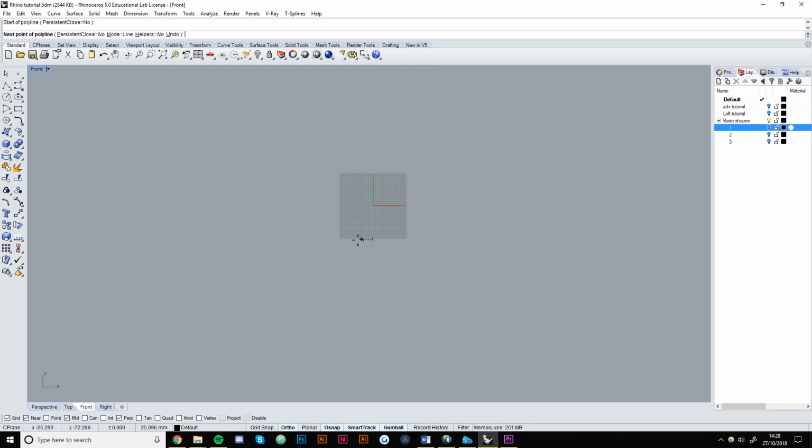So to start, I'm just going to click a point. If we hold shift, it's going to keep that in orthographic. It's going to create the general shape here, not worrying too much about dimensions. So something like that will do. And then we'll finish out by, if we hover over this endpoint with Smart Track turned on down here, it'll then create a guide for us, a temporary guide that we can use to align these 2 points together, so we're ending roughly where we started. And if we right click, we then have half of our shape.